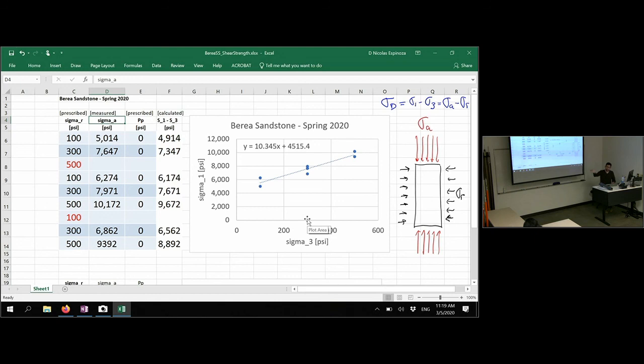From there, you calculate the friction angle and your unconfined compressive strength, which should be close to 0. Don't put a negative value, okay? Even if your fitting gives you a negative value, that doesn't make sense. It should be either 0 or something slightly bigger than 0.